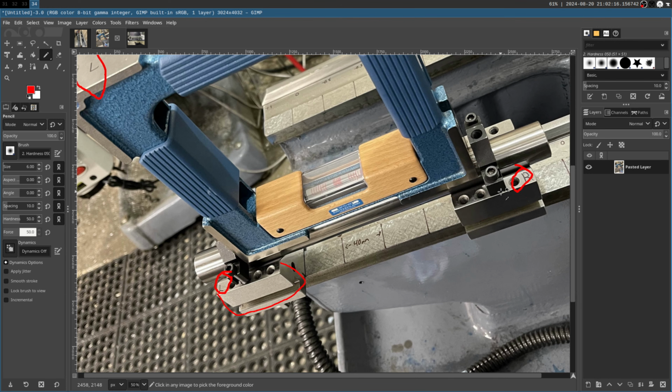So if you set this level down, since this dumbbell setup is only slightly larger than the level, effectively 1 division on the bubble will correspond to approximately 10 micron, right? So I can notice if this is up 10 micron higher, that's going to be roughly 1 whole division. Now, since this is an analog thing, 1 division is actually quite large, probably 2 or 3 millimeters of deflection of the bubble. I can pretty accurately, by eye, notice half of a division.